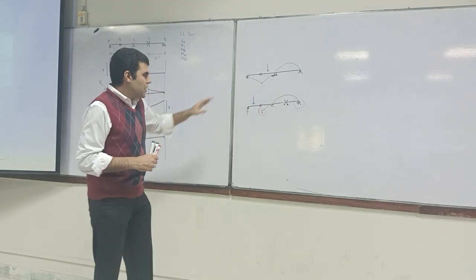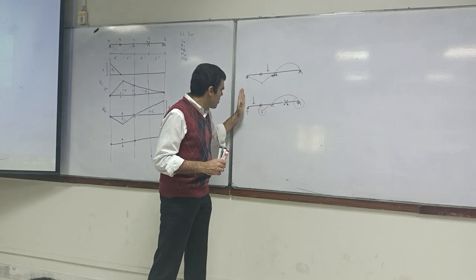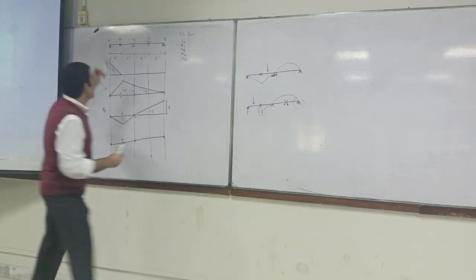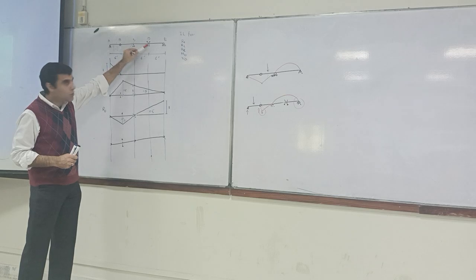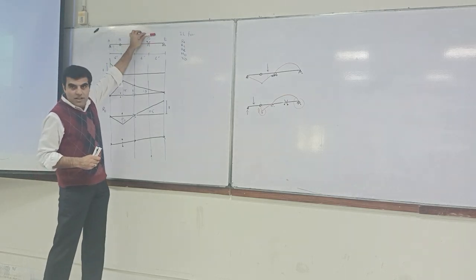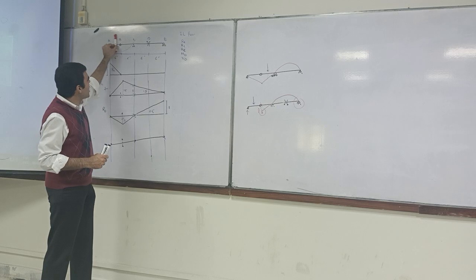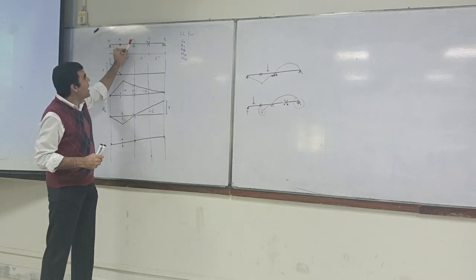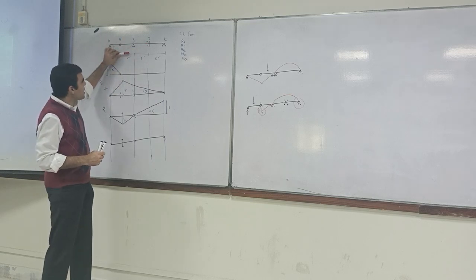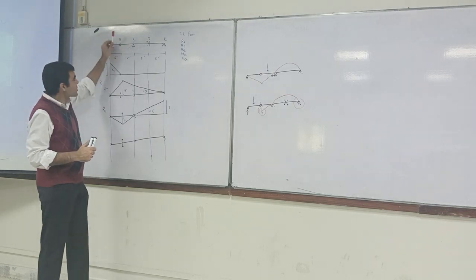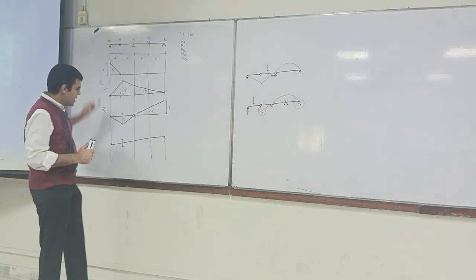From this question we can see that as we move our load, when the load enters this point, this thing will be pushed up. It will lift off. This span will lift off, isn't it? It will move up. So when we are moving it along this point, should our moment be positive or negative? I mean, should it be above or below? Because your elastic curve is up, it should be above.